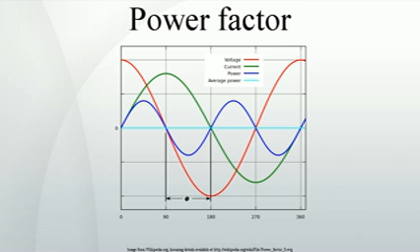Power factor correction in nonlinear loads. Passive PFC. The simplest way to control the harmonic current is to use a filter. It is possible to design a filter that passes current only at line frequency, 50 or 60 Hz. This filter reduces the harmonic current, which means that the nonlinear device now looks like a linear load.